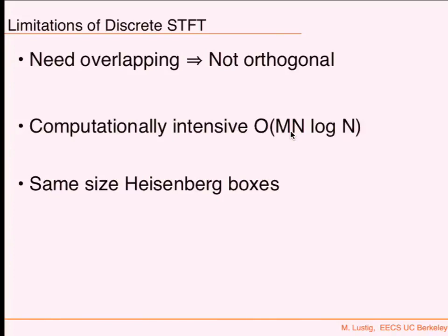So that's nonlinear. One way to do this is to set a threshold, and anything above the threshold might be signal, anything below that threshold is noise. Then you take an inverse DFT and you get back your sinusoid. Statistically, you can pick the threshold, and it's going to be a trade-off between false detection and false alarm and all sorts of other statistical considerations.